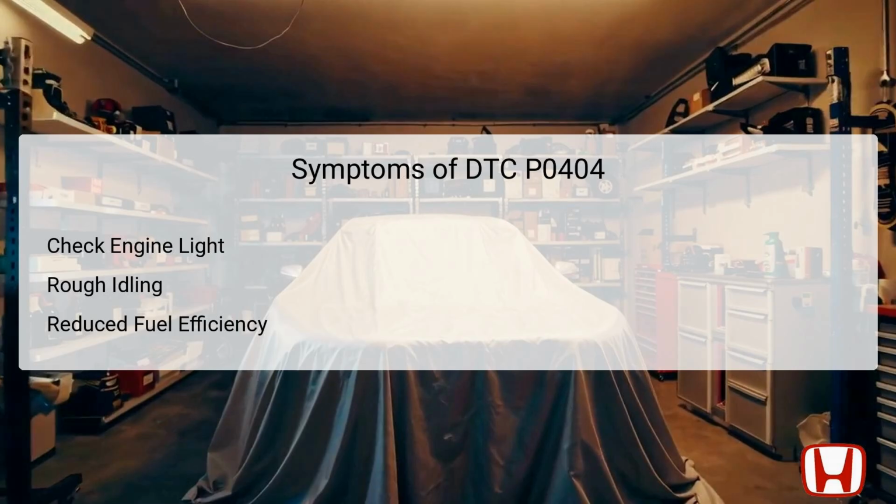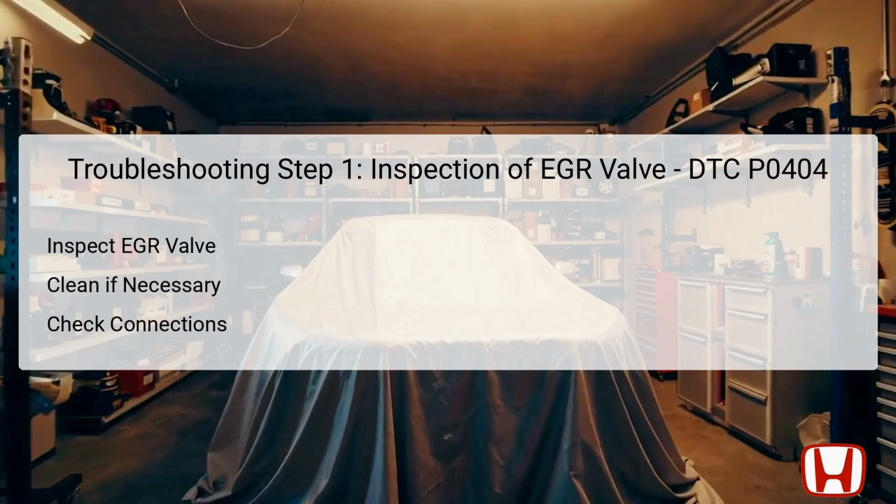Another significant symptom often observed is reduced fuel efficiency, as the engine may not be able to achieve optimal combustion conditions. Recognizing these symptoms allows for quicker diagnosis and corrective action, ultimately maintaining the health of the engine and its performance efficiency. The first troubleshooting step for DTC P0404 involves inspecting the EGR valve itself.